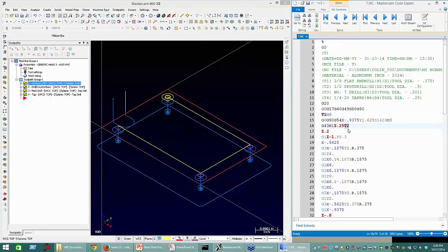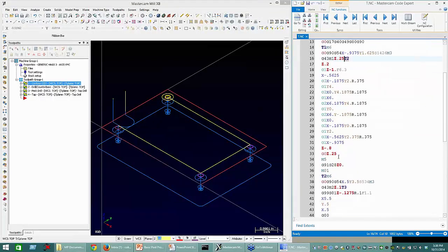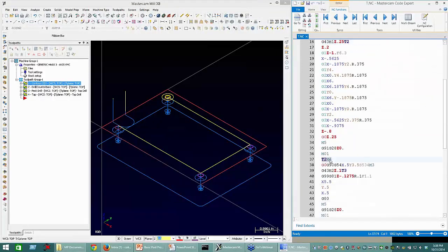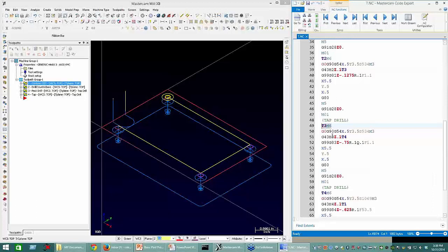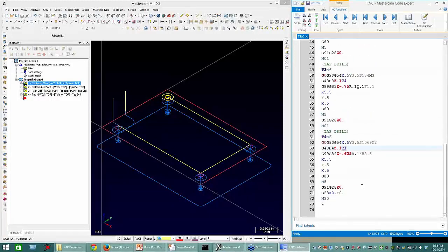So this is going to call up tool 2. It's that pocket ready. And then when we go and do our tool change to tool 2, that tool's already in position, and that happens much more quickly. And then you'll see on the next tool change, here, tool 3, now we output T4 again for pre-staging. And we're pre-staging tool 1 at the end here.